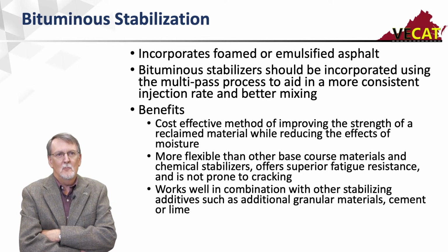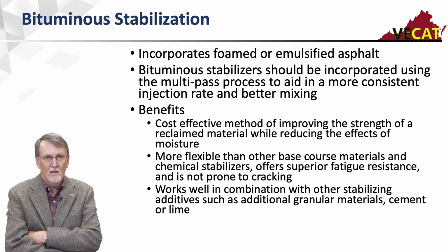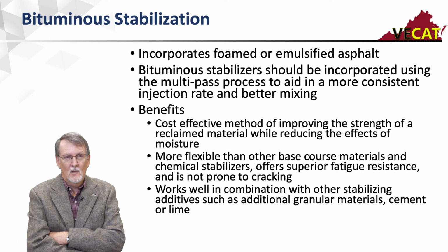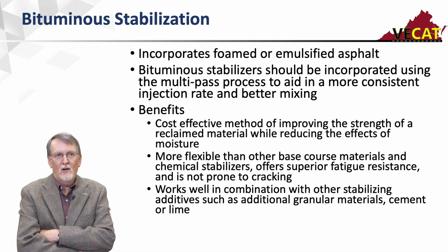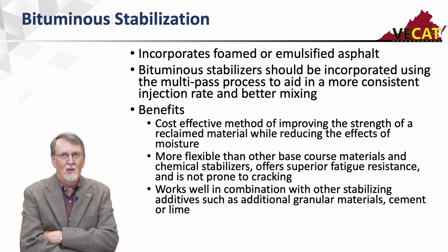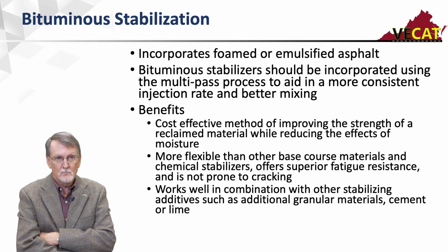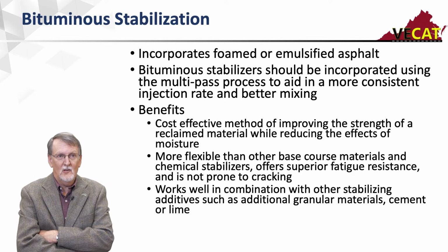It's a very cost-effective method for improving the strength of the material while reducing the effects of moisture on it. And it's more flexible than the other base course materials and chemical stabilizers. So it gives you superior fatigue resistance. It's not as prone to cracking. But it works over a narrower range of materials. The asphalt products don't like a lot of fines. So if your base course is relatively clean, you can use bituminous stabilization.